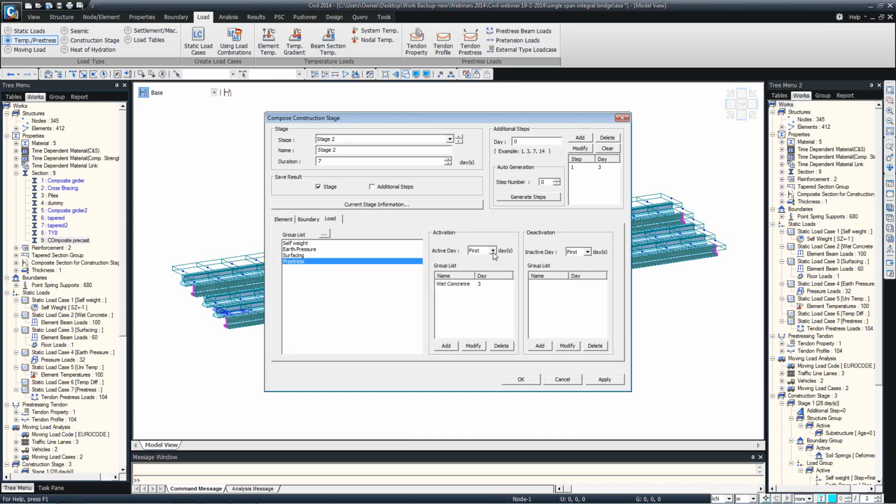we can apply pre-stress on the first day. So when concrete age is 7, the pre-stress is being transferred. Okay, and that's how it will be considered gradually. So most of the cases you can just keep it as 28 days, which will be the full strength of the precast beams. But you can also go for a little conservative by taking into account the initial losses in the precast beams itself.